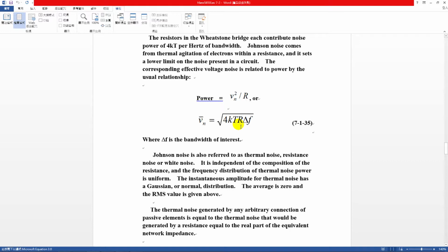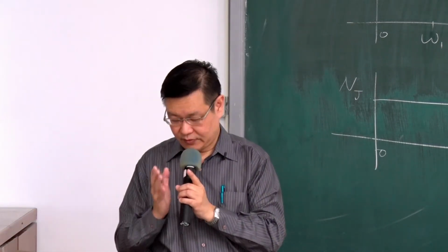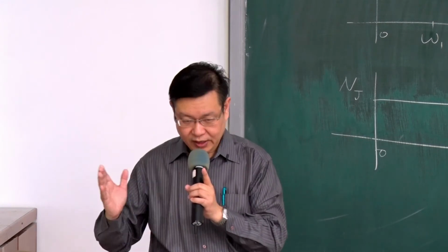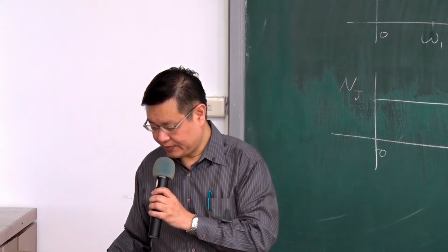However, the noise increases with the temperature increment. So increase the temperature, you also increase the noise power. So you can find the Vn, the noise equivalent voltage, will be this formula, 4kT times R, and also times the bandwidth. The bandwidth means the window, how large the window we open up. This depends on from DC to your natural frequency, how large the frequency response window you have. So we multiply by delta F. Delta F means the bandwidth.